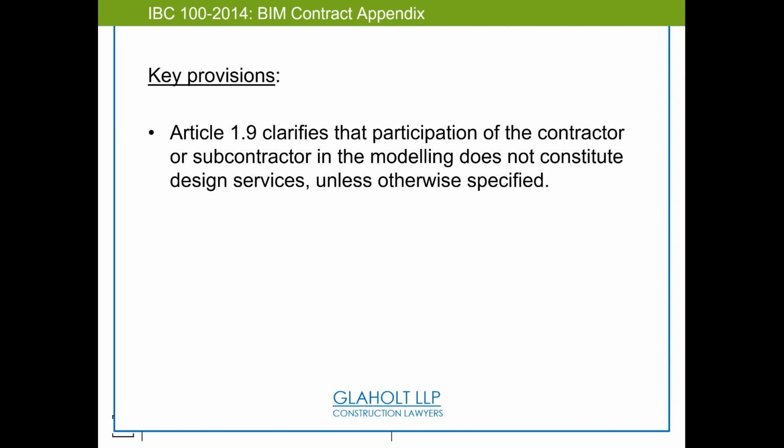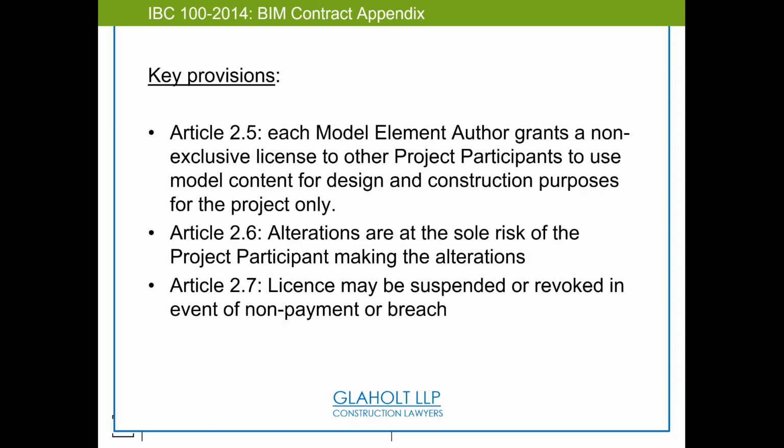We clarify the participation of the contractor and the subcontractor. So if they're doing any modeling, they're not actually designing. That allows us, for example, with modeling of fire suppression systems or modeling of components that are field routed, to say that doesn't mean they now assume the mechanical design responsibility. They're just modeling the components.